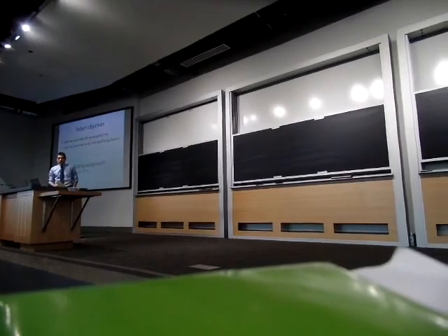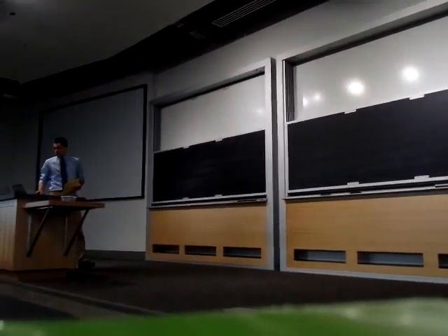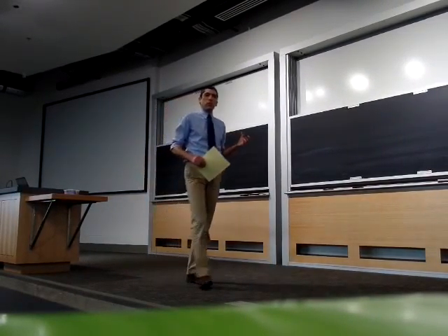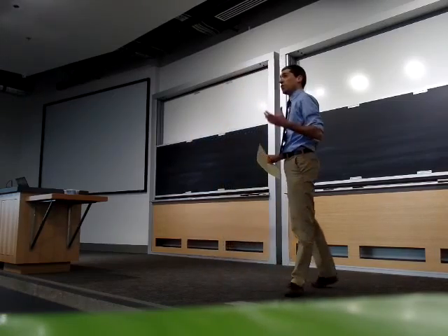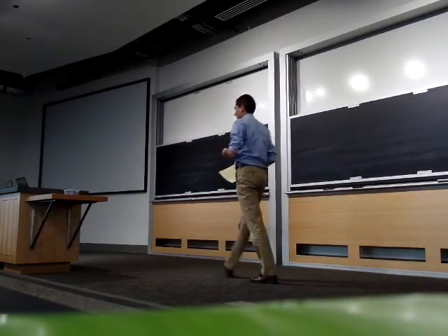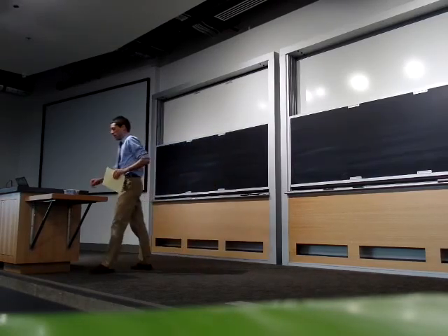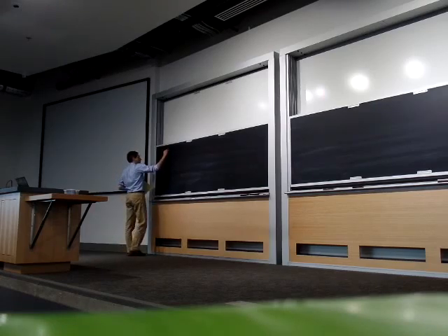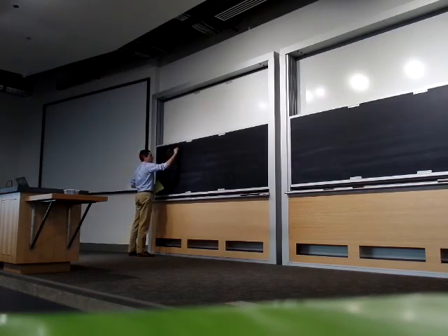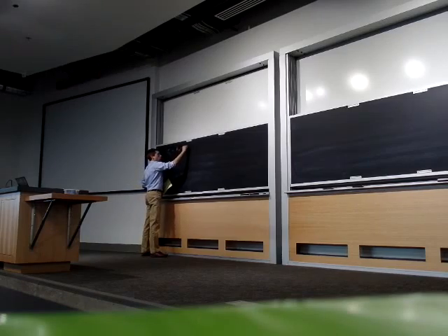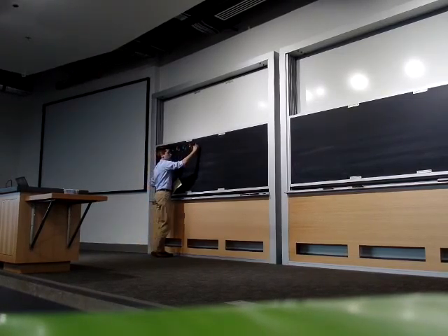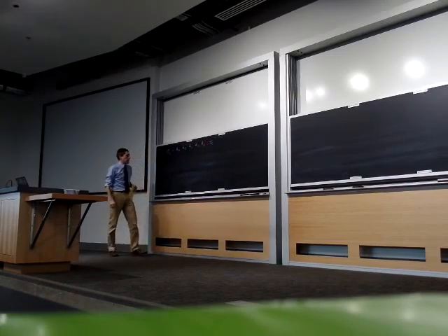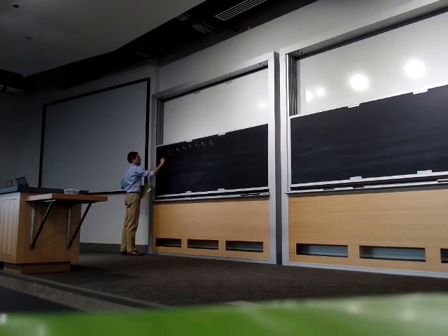So last time we talked about endurance limit modifying factors, and in particular we talked about how to convert from sigma E prime, which was our endurance limit for the Moore test specimen, to the endurance limit for any mechanical element. And we said, well, all we have to do is multiply our endurance limit for the Moore specimen with these endurance limit modifying factors. We had started by going through them.